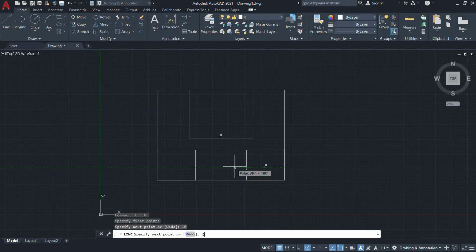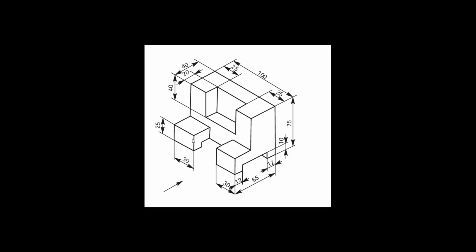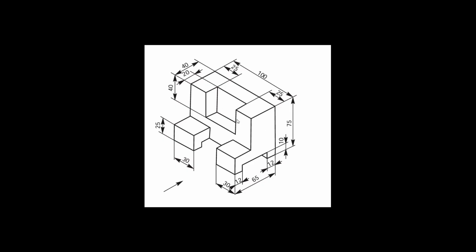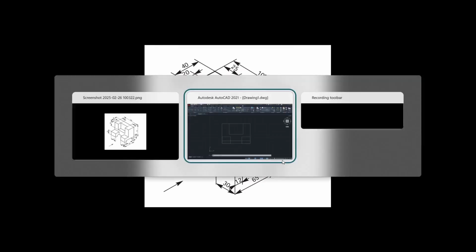It is also mirrored from one portion to another portion. So using mirror entities, type the command MI in the command line and choose this right horizontal line profile, enter it, start from its midpoint and mirror this portion from right end to left end. Same as before, draw another horizontal line profile. It is just to represent the other horizontal edges. Look at these edges, this is represented on the front zone itself. So using a line, connect both endpoints. Now we are going to transfer some of these line profiles to represent non-visible edges called hidden lines.